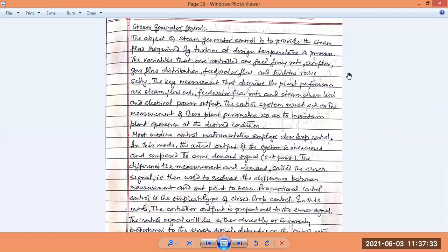Next is the airflow. I have just told you that airflow is the important part which you can control more easily than controlling the fuel and fuel burning rate. So you have to control it, and you have to know how much air is required for this type of fuel to produce this amount of heat, and this should be the firing rate of the fuel itself.